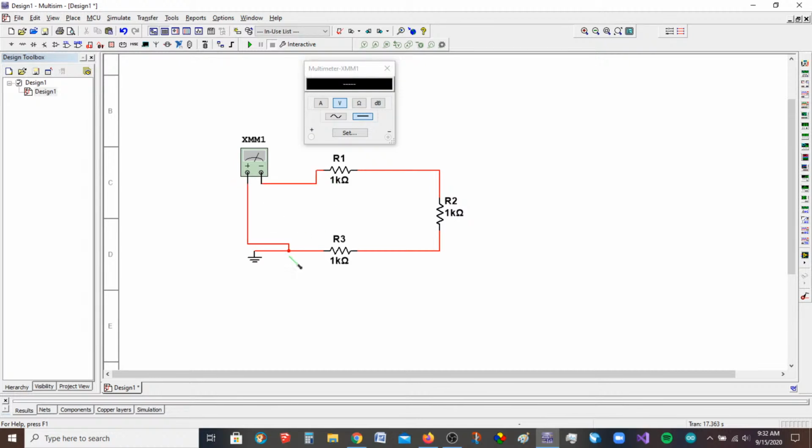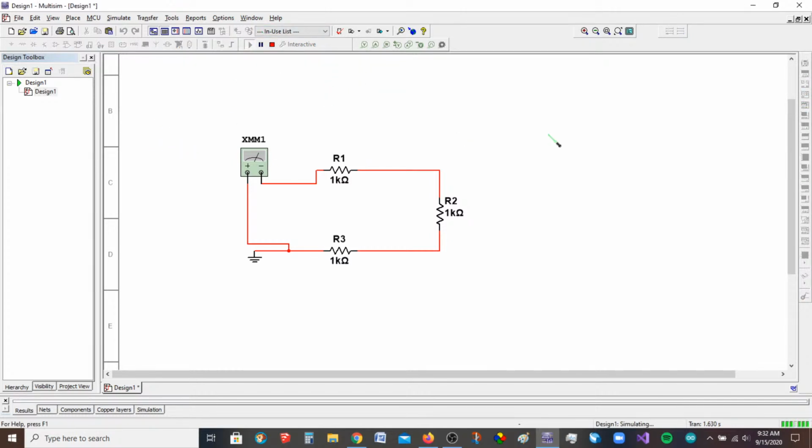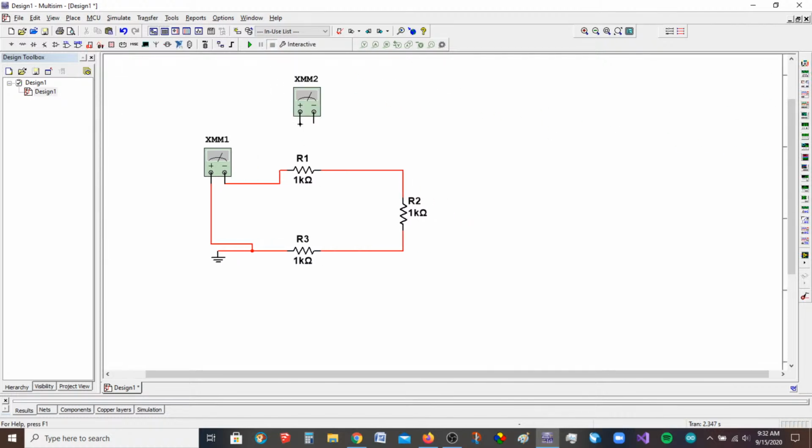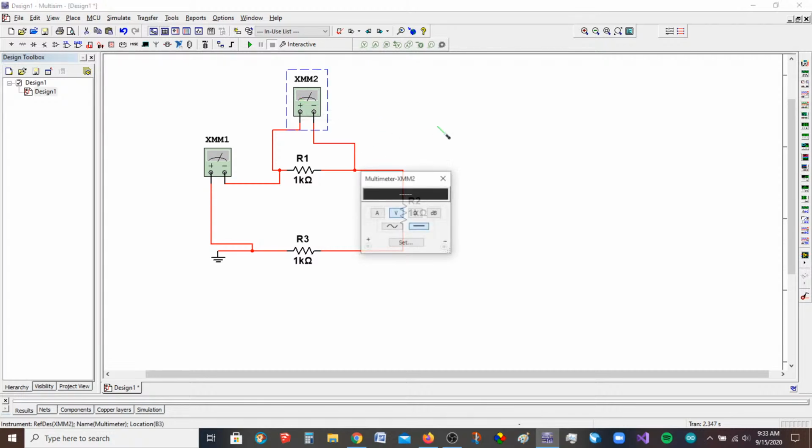All right, so just like in the video, it's going to measure all of this resistance in series, because in series circuits, that's how we calculate the total resistance. We take all the resistors in the loop and add them together. So what you should see here, if I'm in the ohm meter function, is that it should measure 3K total. There we go. Okay, so I can also take a multimeter and come up here and measure an individual resistance. Remember, you cannot have this thing powered when you do it.